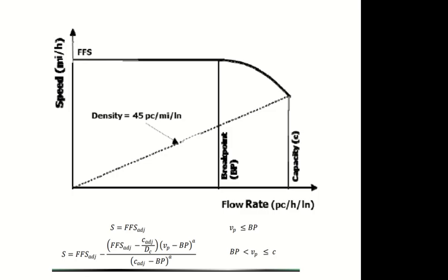So this is the graph which we follow for both these types of highways. The speed-flow graph has speed on the y-axis and flow on the x-axis. I showed something similar in lecture 1, I believe, but that graph was full. This one is only up to capacity. You can see the last point on the curve is capacity.